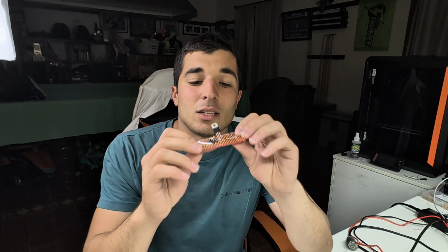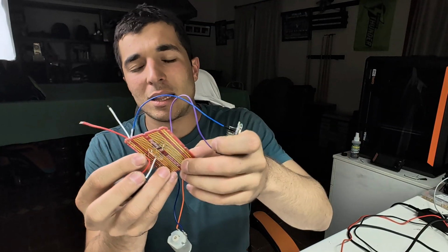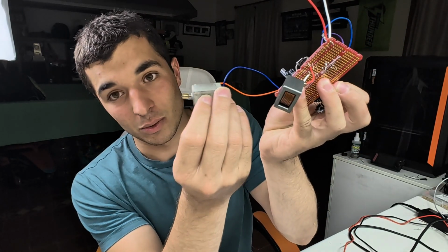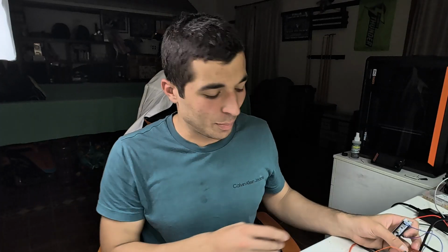There's plenty of ways you can improve this design, by the way. Like, one, use a PCB, two, start closing the loops. I mean, there's so many open loops here. Look at all these long wires that create parasitic capacitance and losses. You saw that oscilloscope, it was just so noisy. It could be because of the motor, but I've pushed this motor so hard it gets abused really badly. But yeah, it might just be noisy. Look how big those diode legs are, just stuff like that. Apparently perf board is good for prototyping, but not good for final design. But at least we got the final proof down pat.